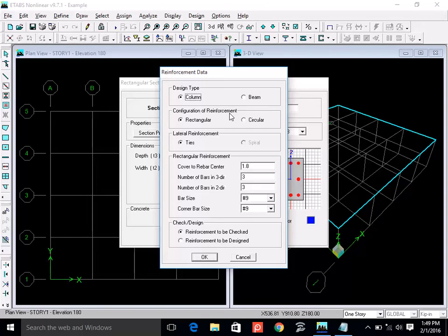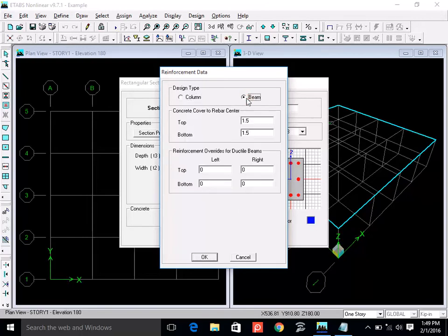Okay, so we were defining our beam, and the cover in inches to the top bar, how much? 1.75. Okay, are you sure about this? Yes, sir. 1.75 inch. If you make it the clear cover 1.5 inch, then this value will be 2.25 inch.